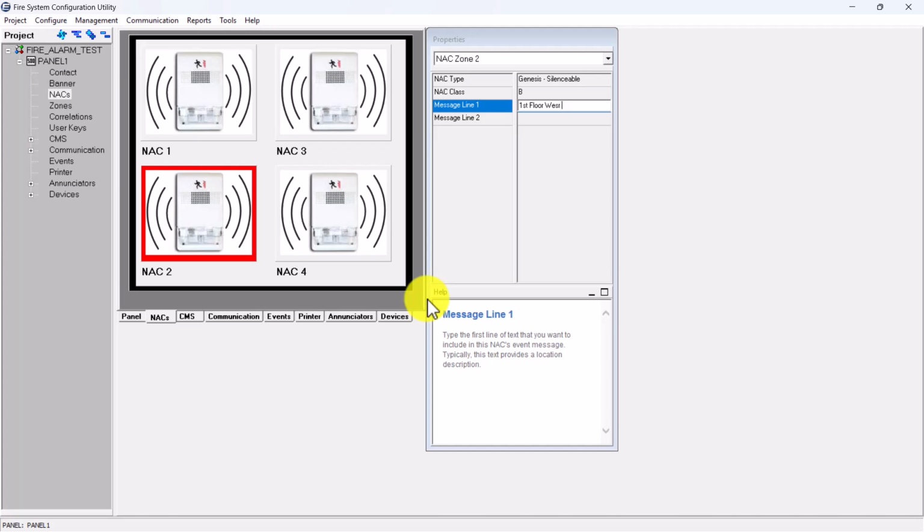And also inside the box, it would be like a grid with dots inside of them, letting you know that the smoke detector should annunciate a signal. It should send a signal to the central station. It should also turn on the horns and strobes. It gives all the functions that each particular device should be doing.